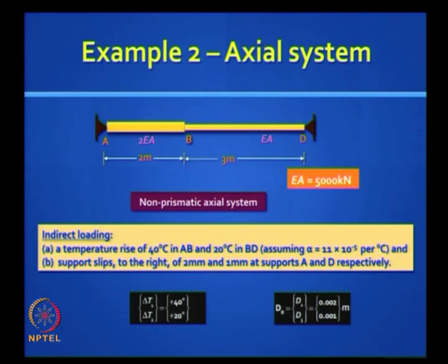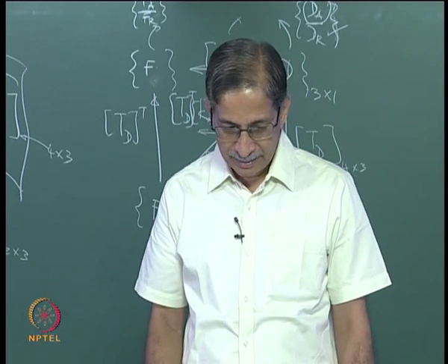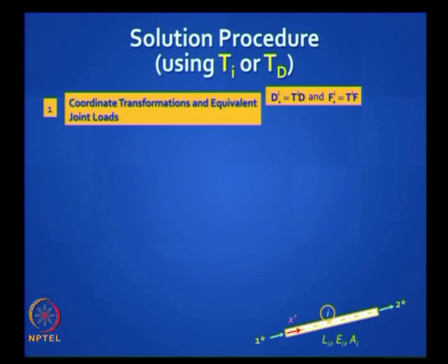How do we proceed? Actually, much of the work is already done because you have already generated your TI, TD, and you have already generated your element stiffness matrix. So it's, your load has changed, that's all that's happened. So you don't need to do any laborious work. Okay, so these are the steps.